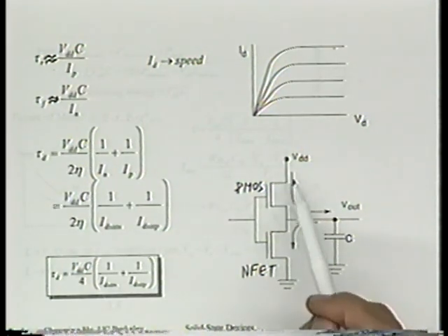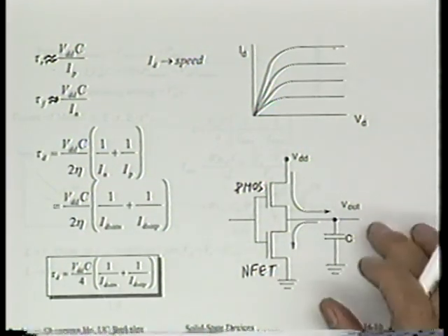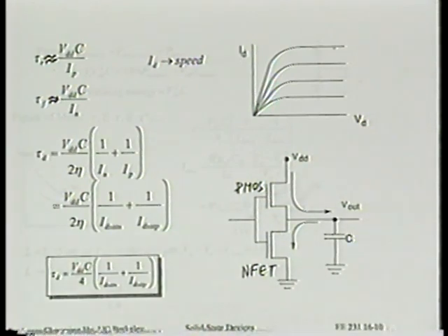By the time it gets to half a VDD, for example, the next stage of the ring oscillator is already switching. Won't you agree? Just think about the transfer characteristics. So that will explain why another factor of 2 comes here. That's why SPICE will give us maybe 3.8, 3.7. You see what I'm saying?